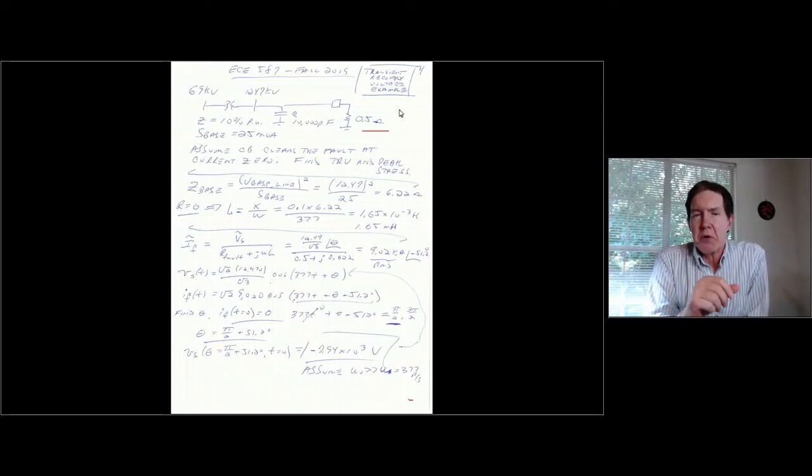Sometimes this is something we would refer to as a high impedance type of fault. A lot of times engineers doing short circuit analysis will do the analysis at 0 ohms, and then raise that fault resistance to see if their protection solutions still work. But we'll assume in this case that the circuit breaker clears the fault at a current 0.